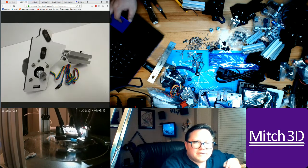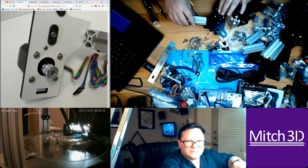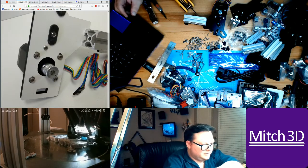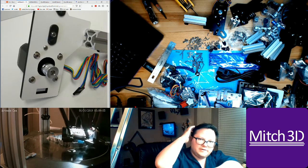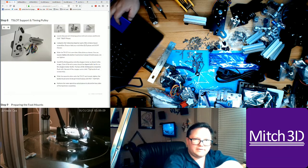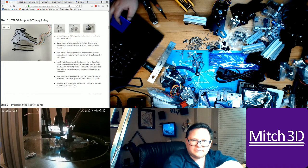That's the pulley flush with the top of the motor. GT2 pulleys have a little bit of give on them, and honestly the idler is going to float a little bit, so I don't think it's a big deal how aligned that is. This is kind of the part right here, so it's allowed to slap in it. Do not tighten.